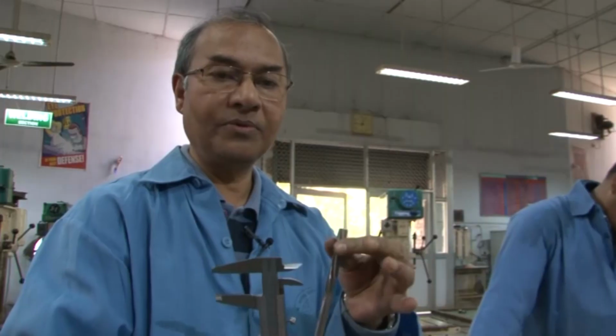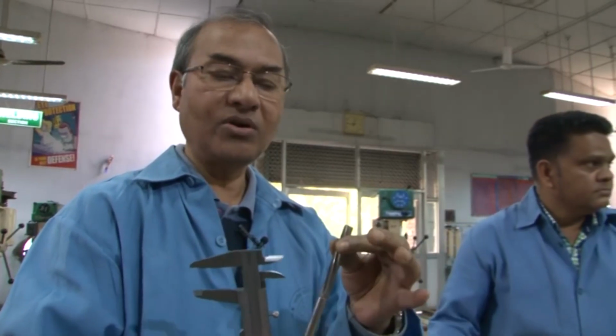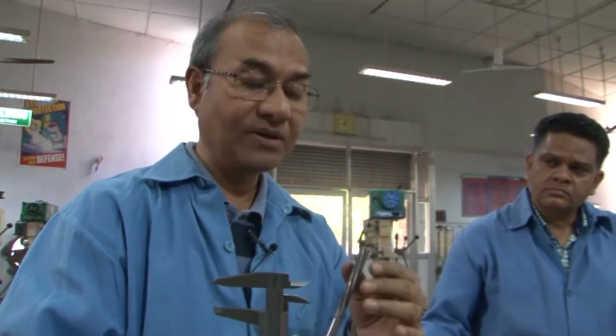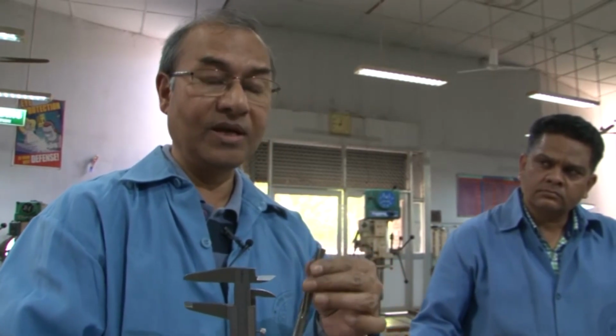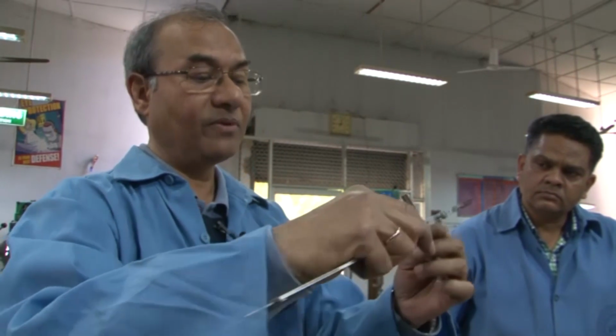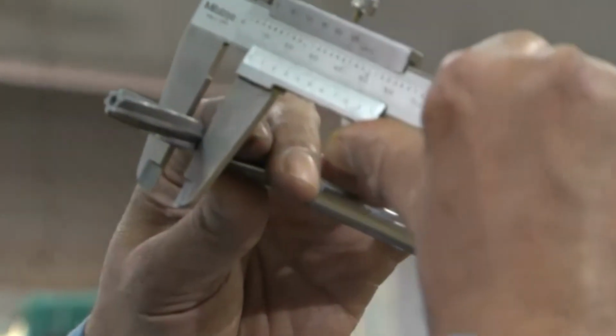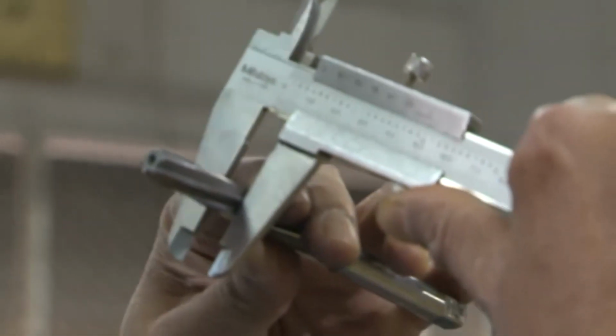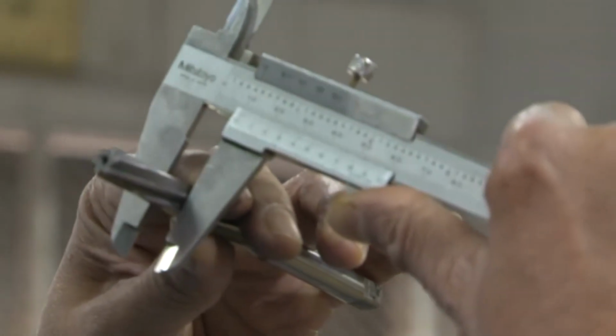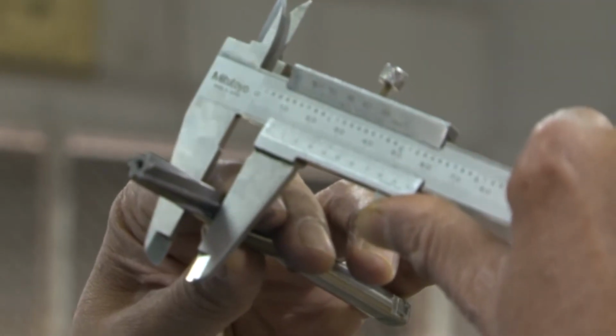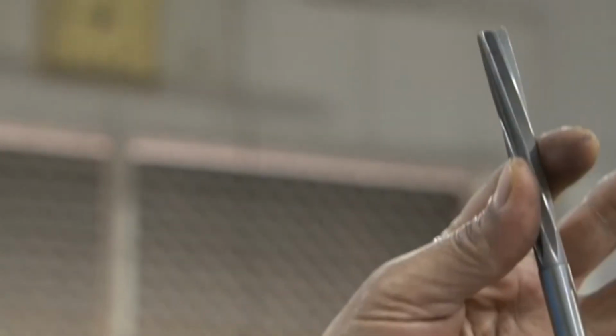The first purpose is that the reamer is an accurate instrument, which means you use it not to remove material as much, but to improve the accuracy. So, you have to very accurately find out the diameter of this reamer. For example, if it is worn out, then the diameter can be decreased. So, according to the requirement of your hole, you can measure the diameter very accurately only when there is an even number of teeth. So, you can measure that this is the right diameter.